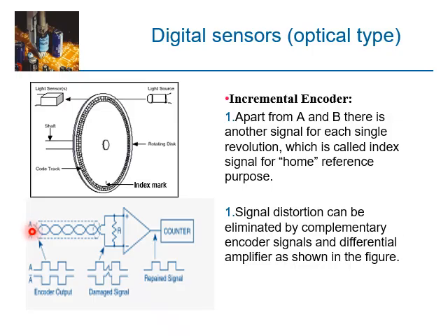So we pass channel A through a NOT gate, so we have a reverse signal. You can see when this is off, A bar is on, and when this is on, A bar is off. Now, once you have this spike of noise, because it is a twisted pair cable, it will be equally applicable to both the A and A bar channels.